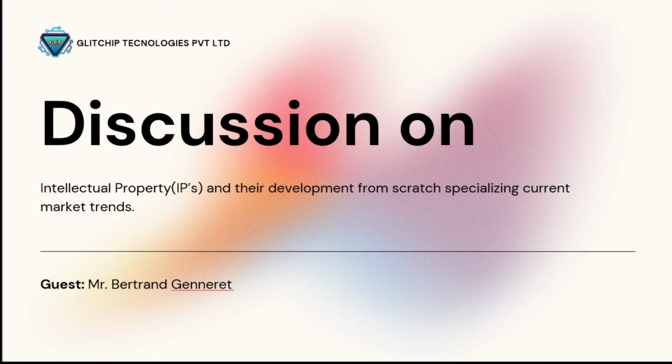For example, you can imagine that you are an IP provider for a memory controller, right? Then you can adapt the entire controller to support the memory vendor, and you can implement the features, and it will require minimal changes when you change the features according to the customer's wishes. So these are the advantages of soft IP I can think of.